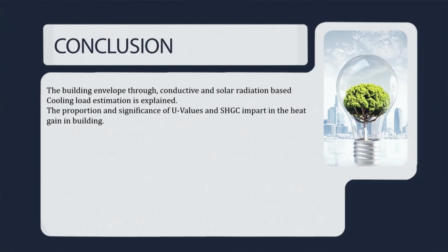but definitely it is an approximate way to find out the heat gain coefficient. We will take this overall heat gain coefficient in the next lecture to see how that will help us to estimate the heat load. Of course, this is approximate, but still we can do that and we can estimate some kind of a heat transfer load.